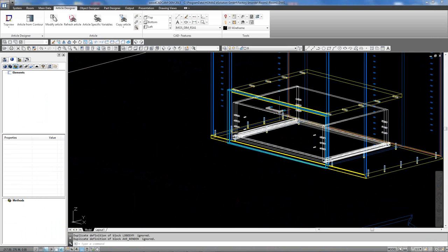We've got variables for pulls created, variables for the slides. You can have as many different drawer box setups as you want. And like I said, we do have a download, which we can go download. Most of the major manufacturers are already preset for you. Let's say you're using Hettich and your database doesn't have Hettich. You can just go download all of Hettich drawer slides, and it sets the boxes up for you automatically.